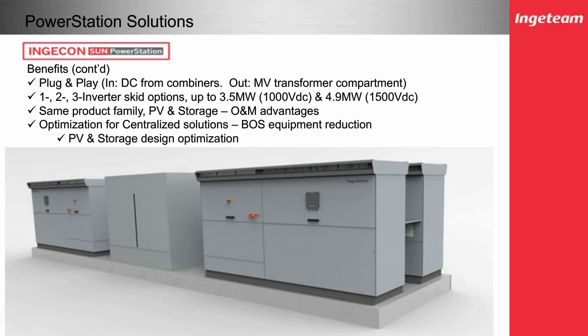The skidded solutions could be 1, 2, or 3 inverters, anywhere up to 3.5 or almost 5 megawatts total of solution, depending upon which battery or PV inverters, the 1000 volt or 1500 volt line, you're taking into consideration. That O&M advantage and spare parts advantage can be utilized because it is the same product family. And in that centralized solution, again, emphasizing that the balance of system does have a cost savings.